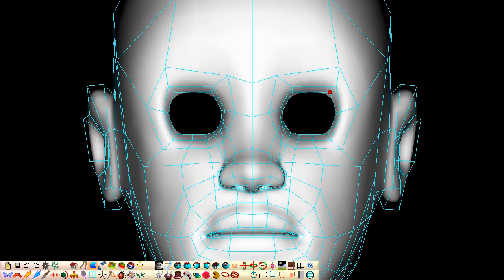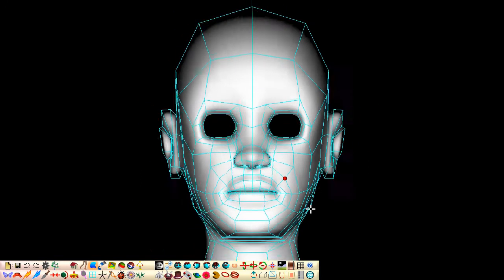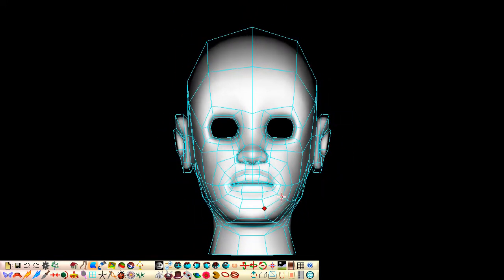Shaping the model is done by moving the control points, and this can be done by simply dragging just one control point at a time from different view angles. But this tutorial will show how you can also select and manipulate multiple control points, as well as ways to make it easier to understand where the control points are in awkward areas of your model.